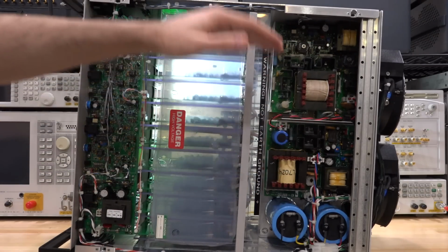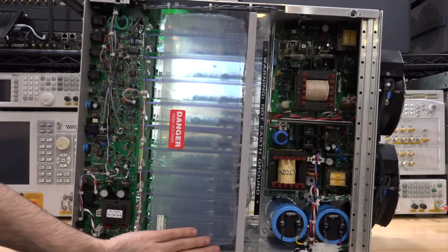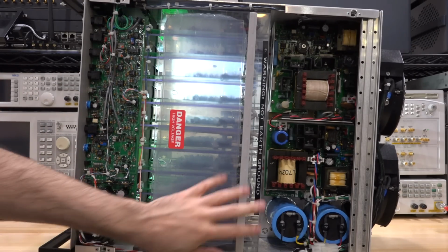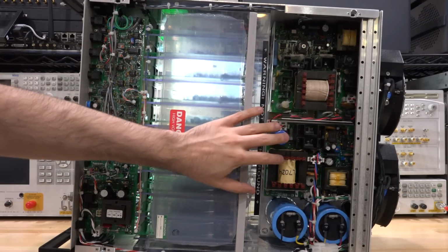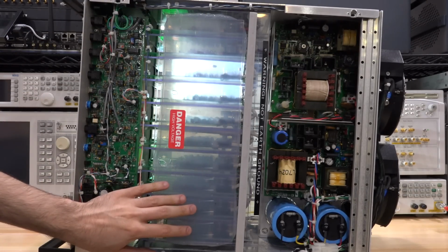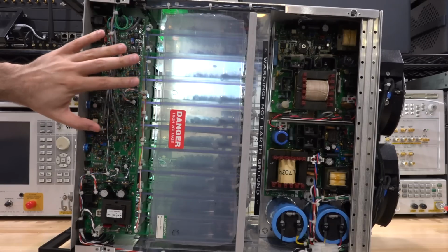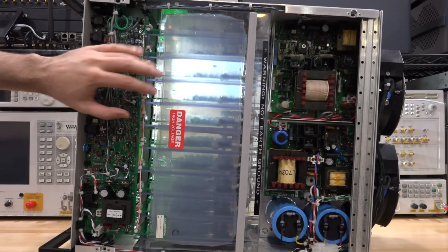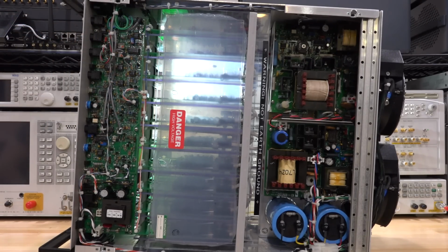The 2 outputs of this just simply feed the top and the bottom of this stacked amplifier chain, which we will see from the other side. The bridge rectifier feeding these capacitors, as I said, smooths everything out, and these power supplies are fixed. 2 big fans just blow over them. So the magic all happens in here. So you're just providing power to this big stack, and then this guy drives them, and everything has to be isolated optically. So let's look through this so we can see how these stages are made.